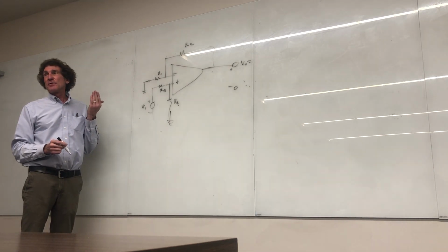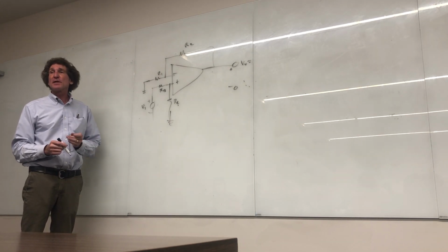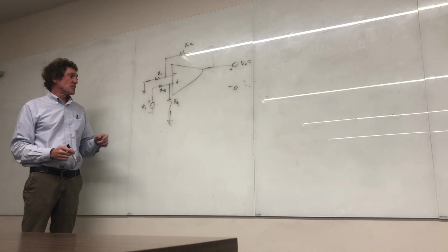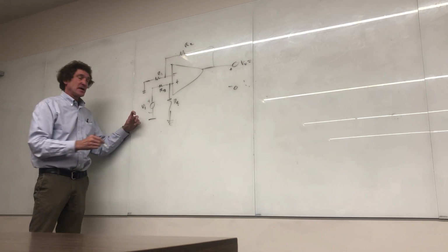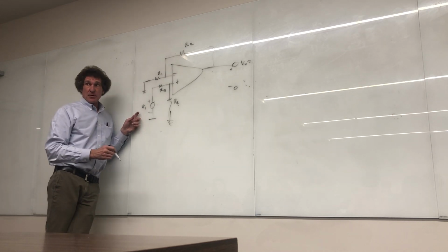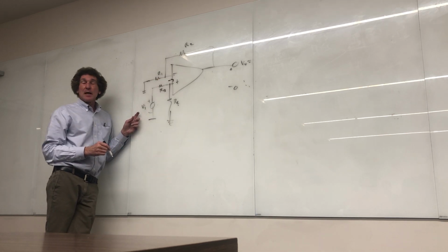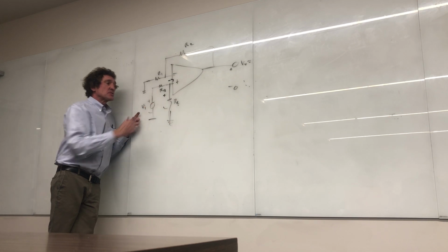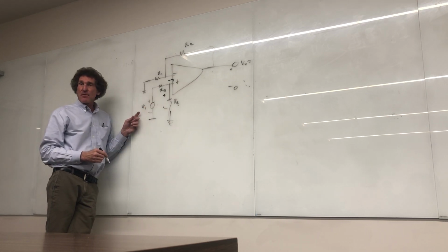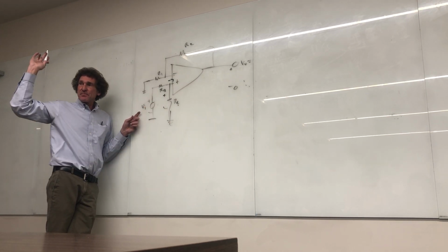So how do we do this problem? Well, what did I tell you? Always find the voltage across one of the inputs, right? Where's the source voltage that's driving this thing? Right here, right? Do you agree with me? Now, how much current can flow into that? None, so really what I need is the voltage across that resistor, right? Y'all follow me here? Give me a show of hands if you do.